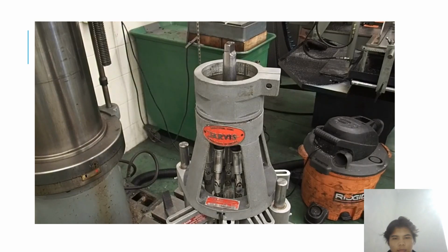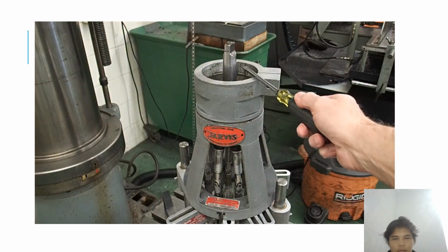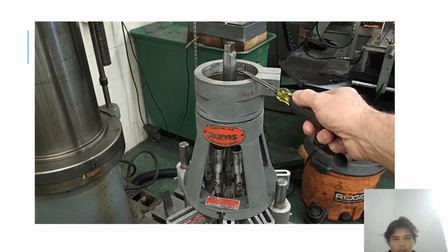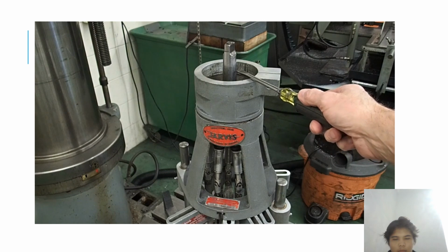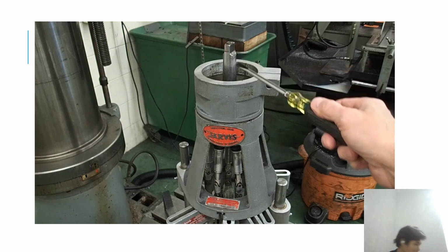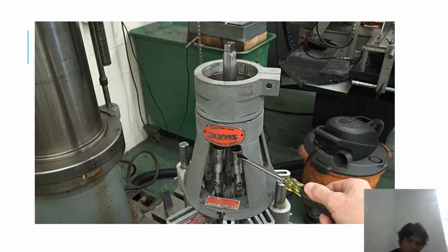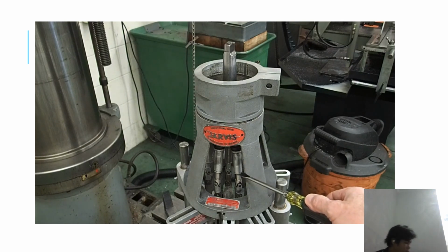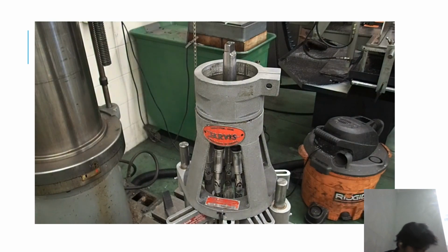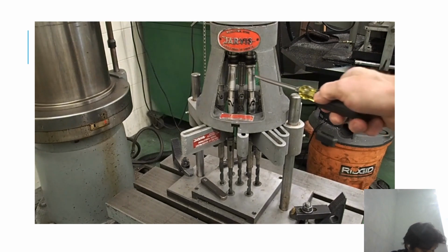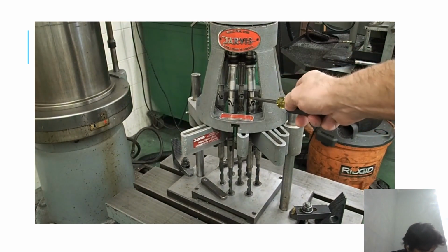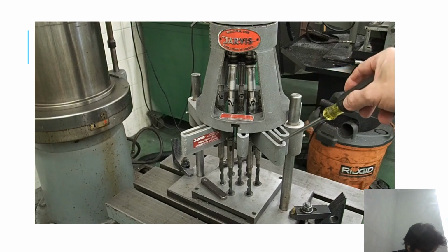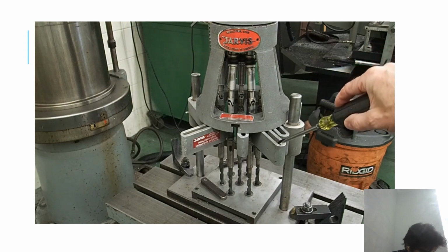This is a multi-spindle head drilling attachment, and what we have is one input here that is attached to, in this case, the radial arm drill press. It's a Morse taper, and as it rotates, it interacts with several U-joints down below, and they will drive different drill bits. These drives are on U-joints, which allows us to set the drills at different diameters by adjusting them on these elongated slots.